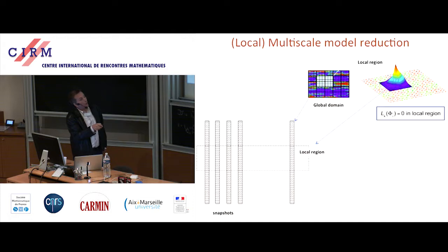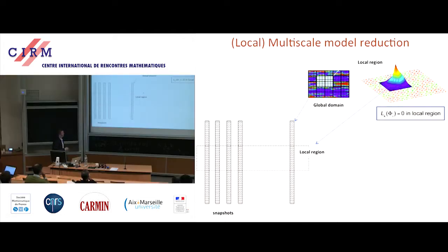It scales like the cost of the fine mesh. So we are trying to address this shortcoming, this issue. Could we evaluate at the local level these quadratures, that is, for example, the basis function, the mass matrix, or the stiffness matrix, that is the gradients of the functions, at a local level without having to go to every single one of the fine mesh cells? So by solving these local problems, then we can solve snapshots of the global problem, and from these snapshots we will derive our global approximations for input-output.